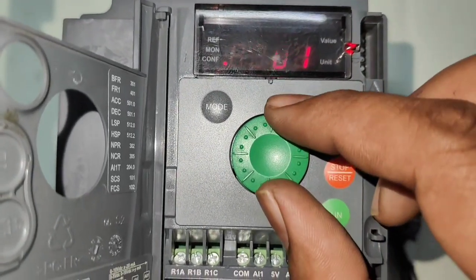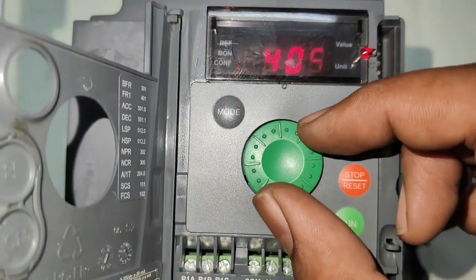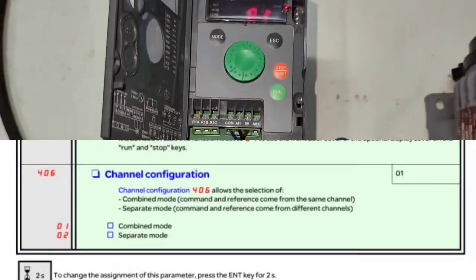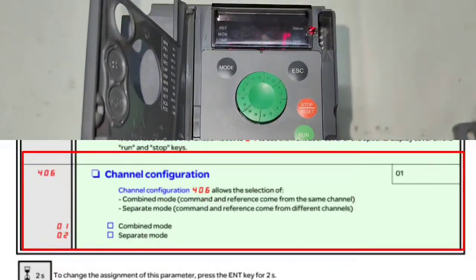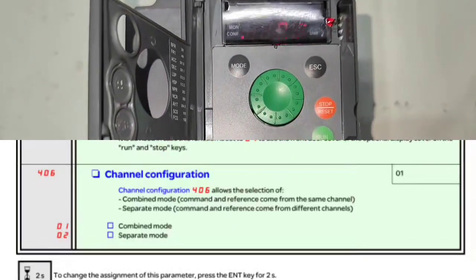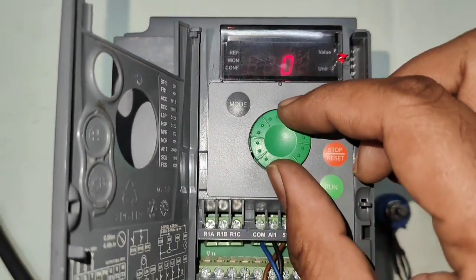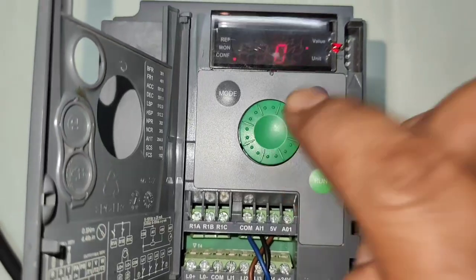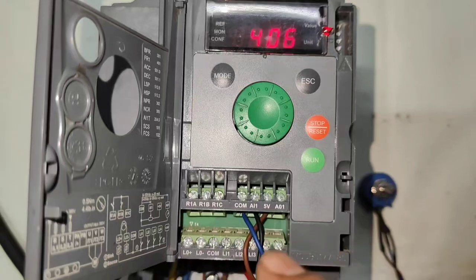Now the next parameter is 406, channel configuration. It's the most important parameter if you want to start and stop your drive by push button or local mode, and if you want to control your drive frequency with the potentiometer or drive keypad. Just set 1 for combined mode. That means your drive will start and stop remotely, and frequency control is with the potentiometer. If you want it different, that means frequency control with the potentiometer but start and stop with the drive keypad, set 2 for separate mode. For now, we set separate mode.